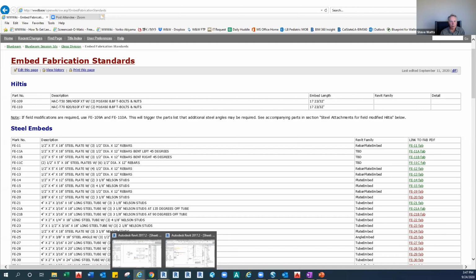Because I think it's a good point. That's not always going to be clear. So knowing it early gives you a chance to let everybody in the system make the stuff they need to make and get it all to you. If you do the whole building and then you go to do your embed drawings and you find out you're missing an embed, now it's a rush because you need it to get your drawings done and everybody needs it to order it and everything else. So. Right. Cool. That's a good idea. I like that. Thank you.